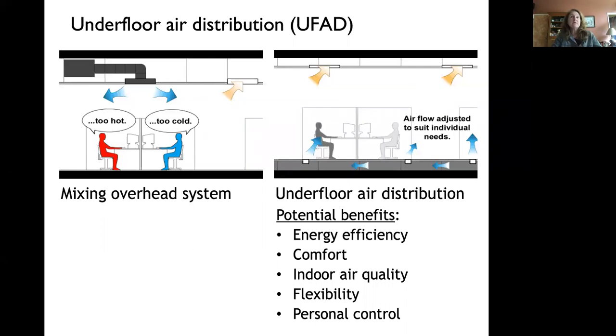It's similar to displacement ventilation in the way that it's being delivered low and extracted high, but UFAD generally encourages a little bit more mixing within the occupied zone while still allowing the stratification of the warmer polluted air up above. But it's a little bit more thought about lower, higher zones rather than a continuum.